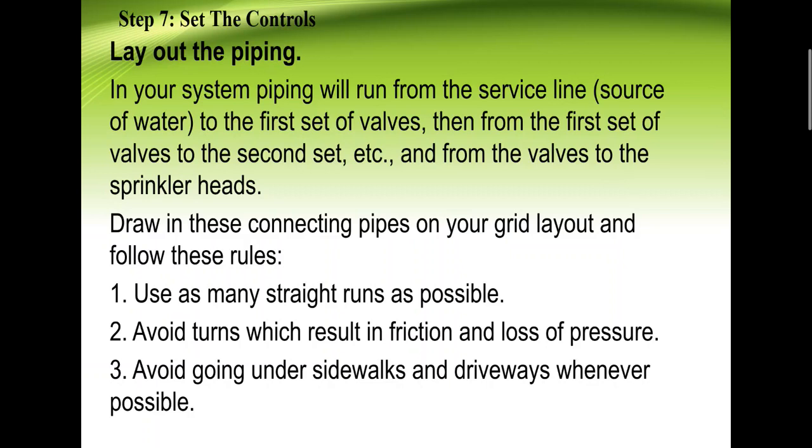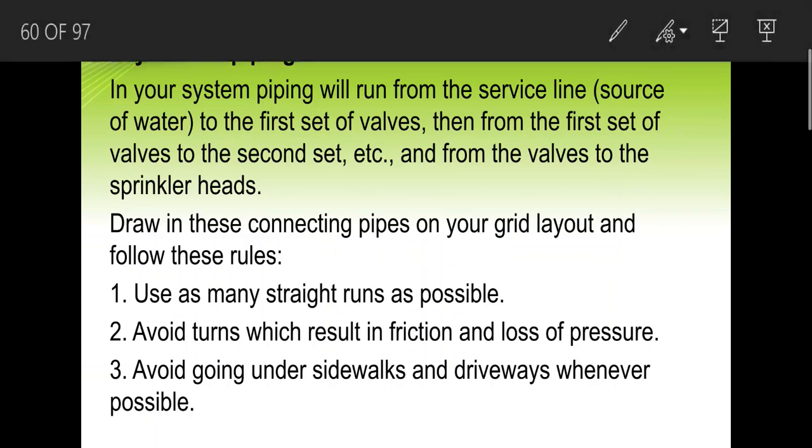Draw the connecting pipes on your grid layout and follow these rules. Use as many straight runs as possible. Avoid turns, which result in friction and loss of pressure.